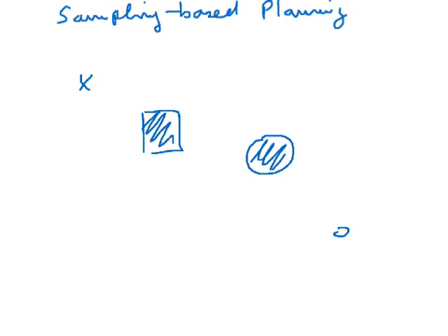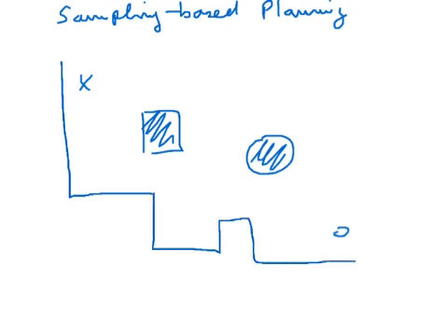This is a simple 2D example, but it could be any dimension. For instance, in a state space which has 6 degrees of freedom, such as x, y, and z position and pitch, yaw, and roll, or the multidimensional degrees of freedom of a high-dimensional arm, where each axis in the state space corresponds to a joint angle, for example. Usually the state space is bounded. These are either obstacles that cannot be penetrated or simply given by the kinematics of the robot platform.